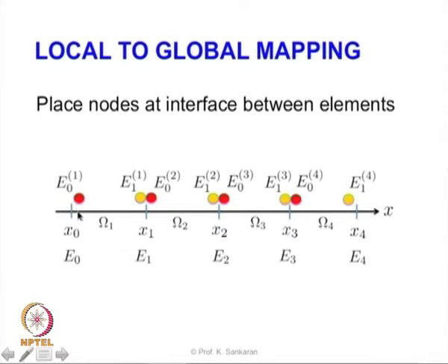So we have the left point and then the right point. Similarly, inside each of these physical elements we have a left point and a right point. These individual points are called the local degrees of freedom. We call them local degrees of freedom because they are locally assigned to the physical element. Similarly, there are global degrees of freedom which are represented by E0, E1, E2, E3 and E4. They are assigned directly to the number of nodes inside a domain.